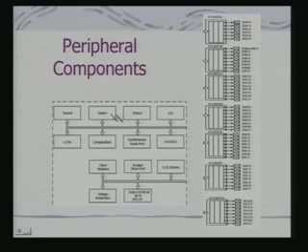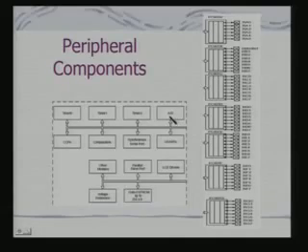In fact, I have shown you 3 timers here. These timers are different from the watchdog timer. The watchdog timer is a special purpose timer. These timers are application specific timers, which means you are expected to program them depending on your application requirements. There is also an analog to digital converter block to receive analog inputs.